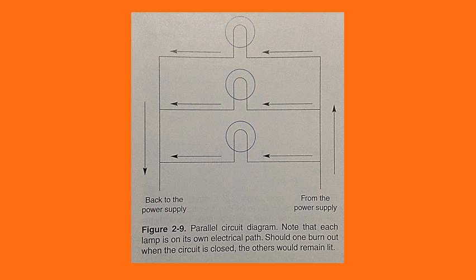Under normal conditions, another advantage of parallel circuits is that the current draw of each branch affects only that branch. In a series circuit, current draw in one load affects the rest of the loads on the circuit. Loads such as lamps, heaters, or motors might not operate properly in a series circuit. Except for switches, fuses, and circuit breakers, all residential wiring is done in parallel.